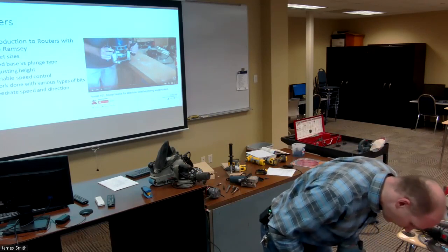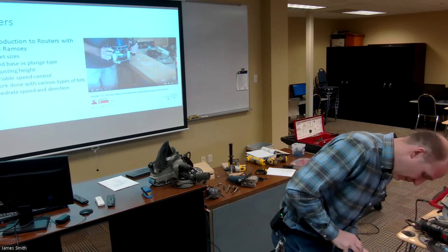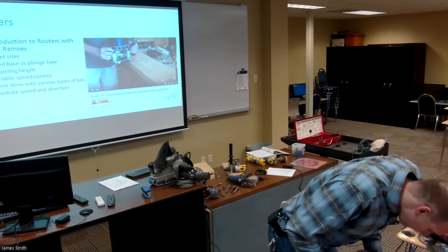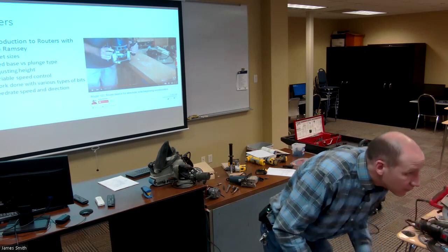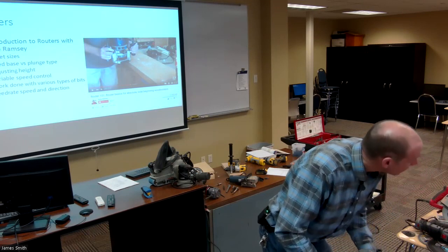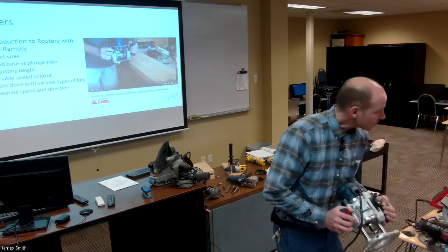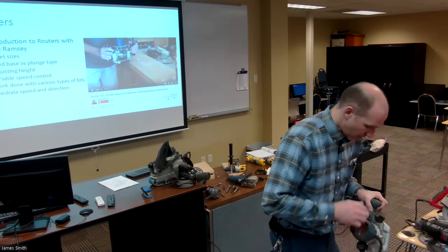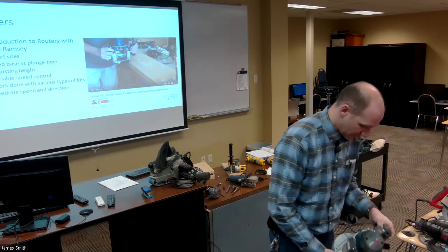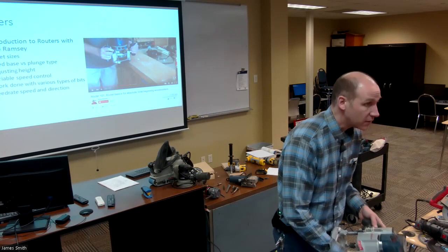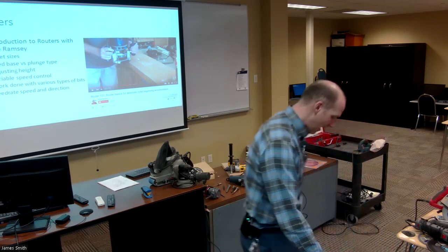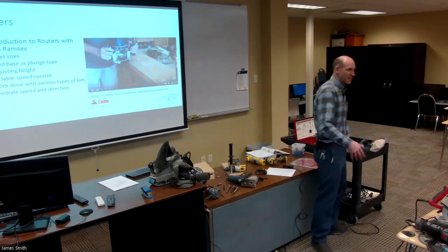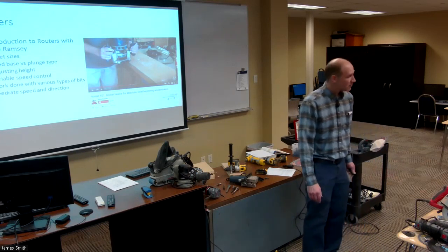Plunge down, cut it, run your cut, and then you can return it back up into the top position. So that's called a plunge router. Got your trigger here. You've got some minute adjustment here. It's a good tool too. But again, they're heavy, they're big, they're awkward. And unless you've spent significant time using one, sometimes they're hard to use.